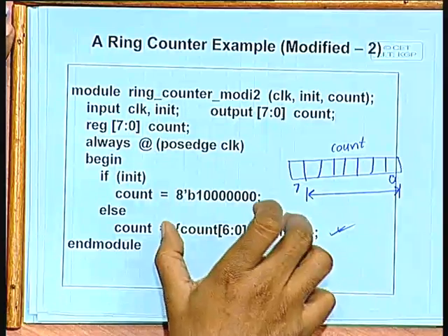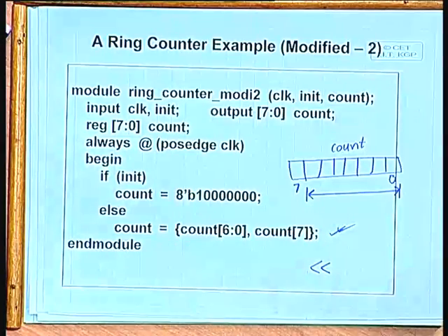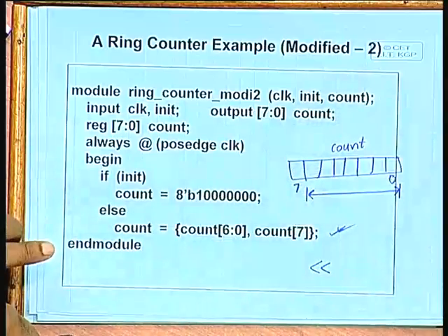So, if the synthesizer can find out that it synthesizes to something which is already there in the library, it can simply pick it up from there. Otherwise it may have to reinvent the wheel, use flip flops to implement this. So, the area will be more, delay will be more, because the designs in the library are highly optimized. That is the advantage.